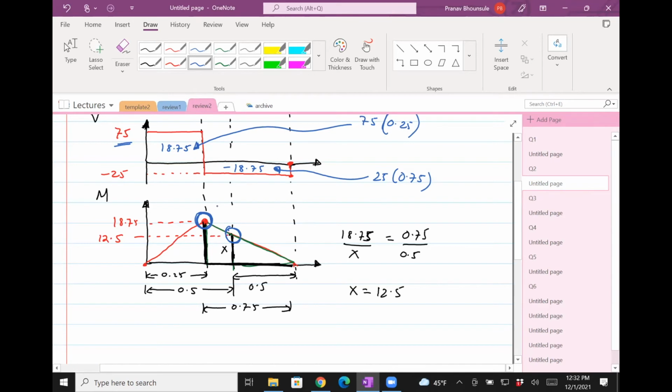So let's call this point A. So A there is the max moment, and the max stress is going to be at that 0.5L. We don't know right now. So that's what I'm saying. We need to compute the stress at A and at 0.5L, and then the maximum will be the normal stress.